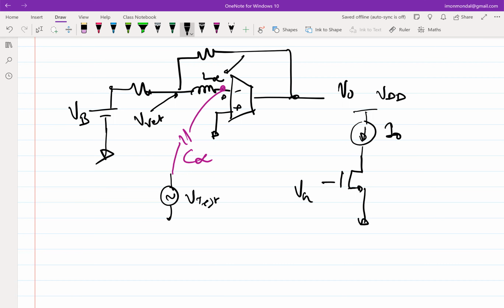Pardon? Yeah, right. So one might say that, since there is no connection to VG, you don't have any business in saying that the VG has been set to the value appropriate to I0. The VG can be anything. Maybe it had some voltage which got coupled when you started the circuit. It can as well be zero.